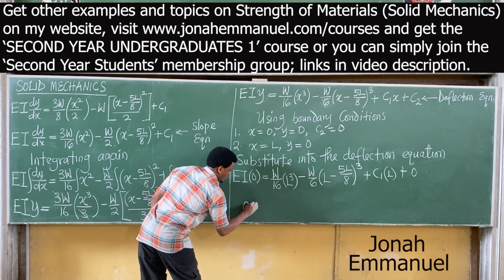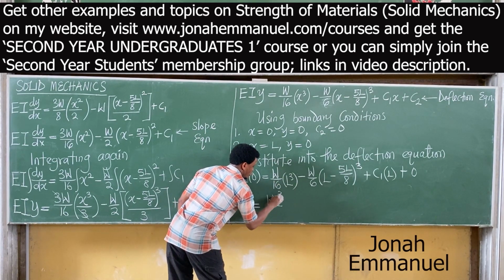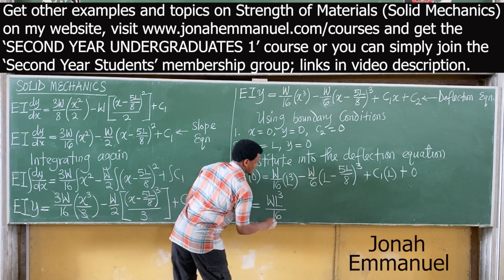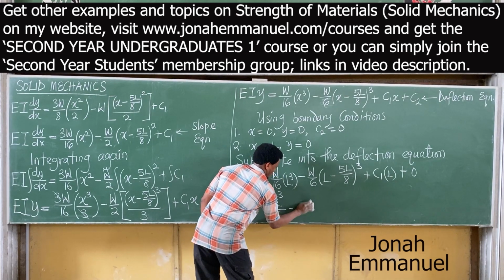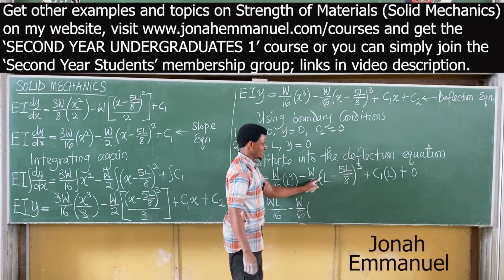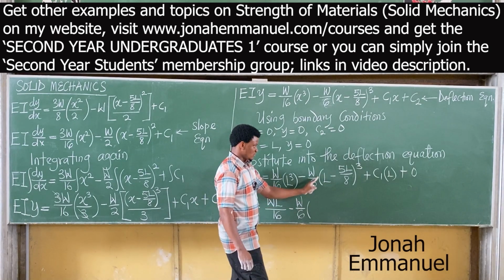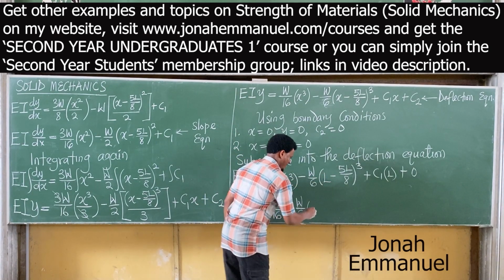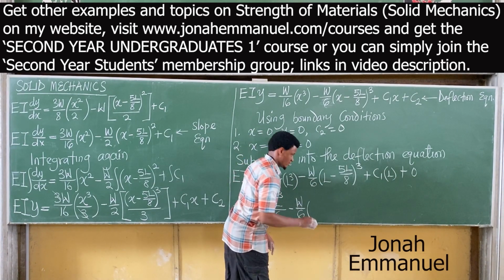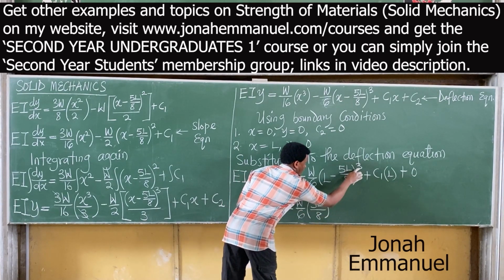This gives you 0 equal to WL cube, W times L cube, all over 16, minus W over 6 into, this is literally 1 minus 5 over 8. What do you have? So this is 1. So 1 minus 5 over 8. You have 3 over 8. There's an L, so 3L over 8, all to the power 3.